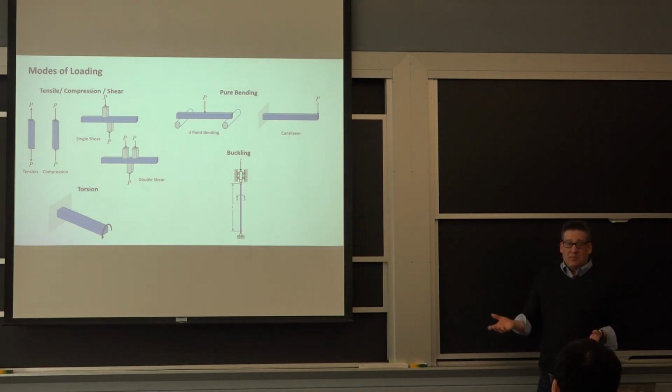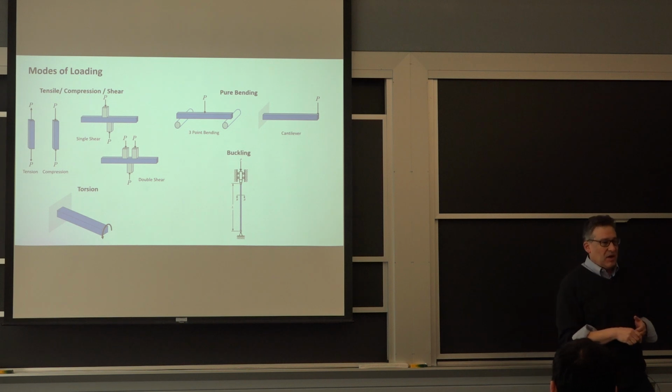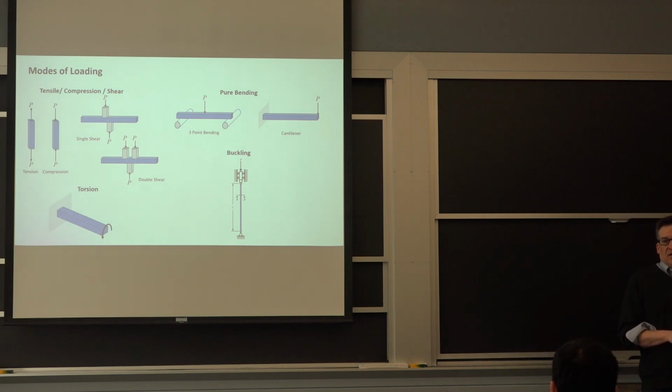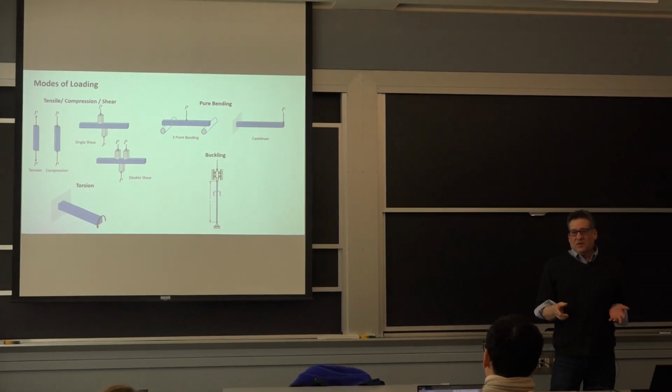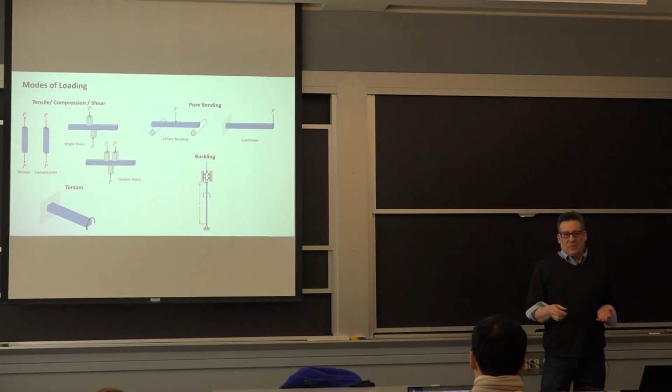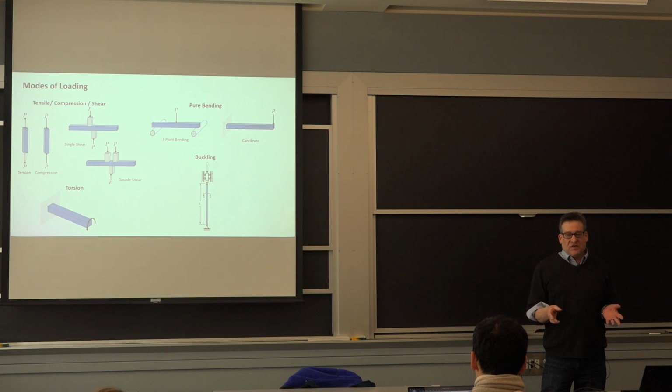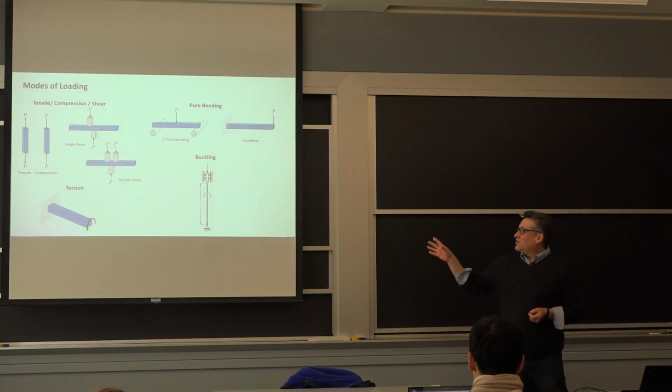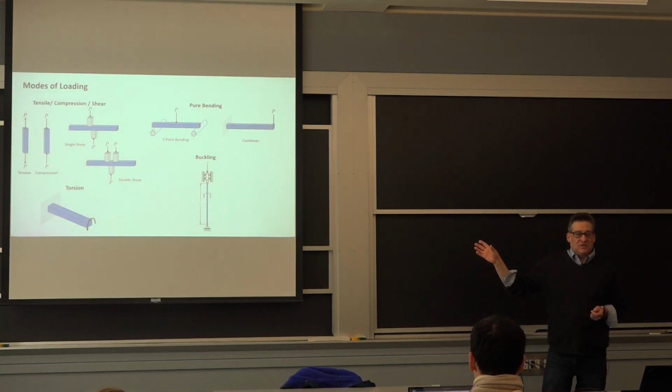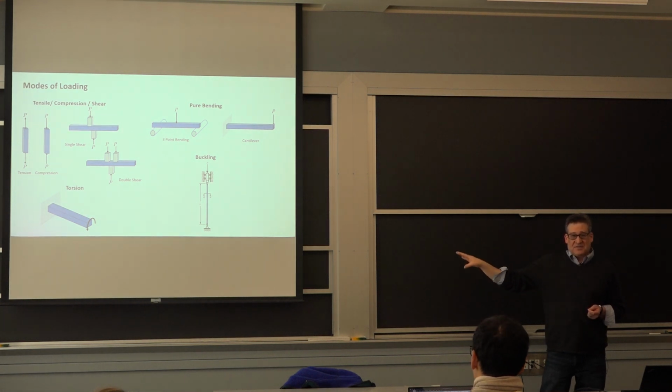And then there's buckling. Buckling is a stability problem. Usually something causes a local instability. One minute your beam under this compression load is holding load just fine. The next minute it gets upset and bang, it breaks, goes unstable and bends out of the way, and you've got a big problem. Okay, so these are really the fundamental ways in which a beam can be loaded. This is really important. I want you to remember this. Any questions about this?